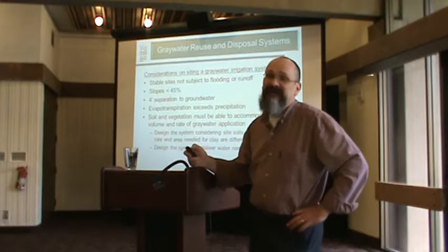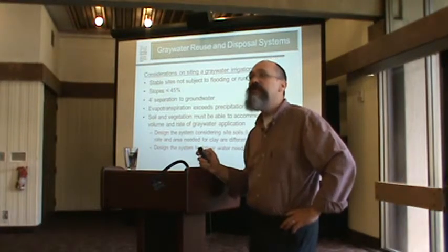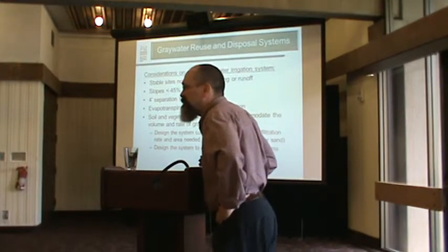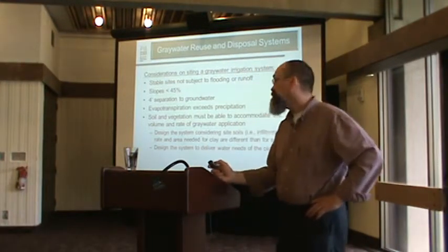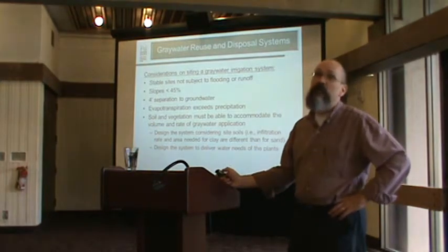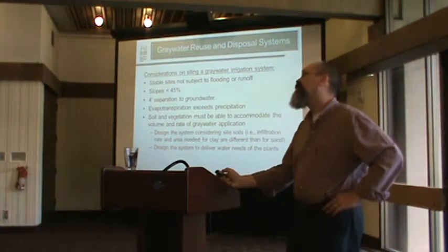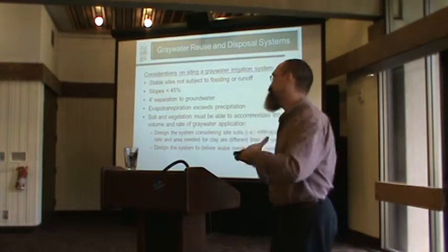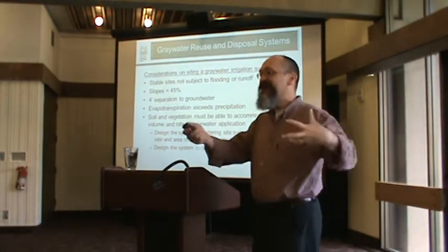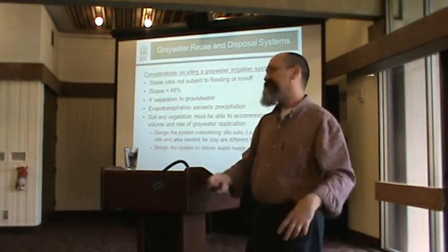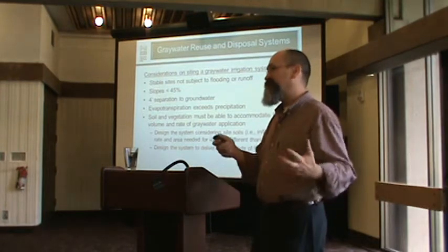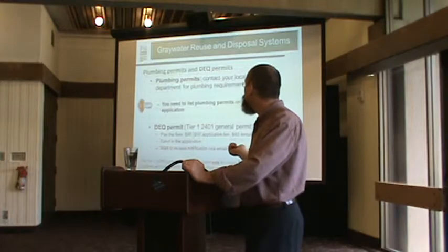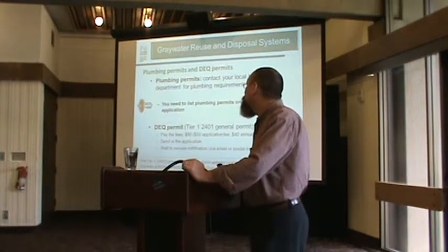We've gone through these, but I always bring them up. It's just know your site when you're putting in one of these systems. If you're a landscape person, know the site, understand the site, know what the soils are like, understand the vegetation and what the needs are for water. Can they take gray water? Are there pH limitations? Know those sorts of things. I go back to that all the time because we're really talking about natural systems here, and you don't want to destroy your natural system by putting nasty things out there, putting water in an inappropriate location.